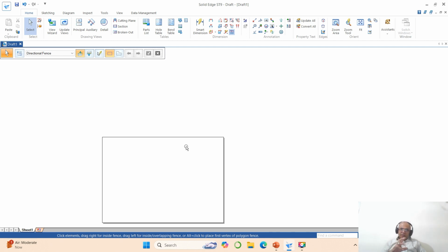So why do I need to set the sheet to A4? Because in examination we need to take the printout only on A4. Suppose you do the problem in A2, then if you try to take the printout, the drawing will shrink, because whatever is inside this boundary will be taken. So automatically the sheet will become big, whereas the drawing will become small. Therefore it is very, very important that you first fix the sheet size and only then start with the problem. Now once you do that, the display has not changed. The display is still set to A2 only.